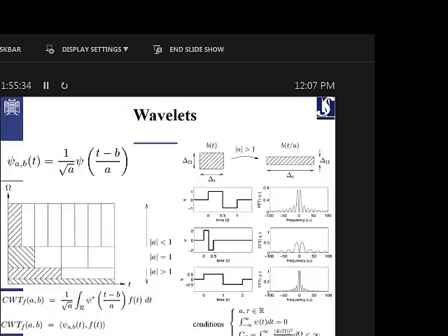Why? Because for low pass filters, where omega is, for example, 0, the filter gives you some value. If you put 0 here and you have a value in the frequency domain, then it becomes infinity. So it doesn't work. But if it's band pass, for the lower frequency 0, you might get 0, and 0 over 0 is ambiguous.